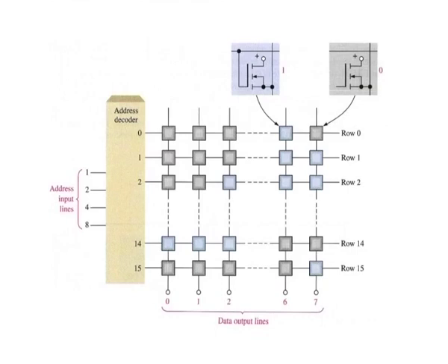This high is connected to the column lines through the transistor at each junction or cell where a 1 is stored. At each cell where a 0 is stored, the column line stays low because of the terminating resistor. The 8 data bits stored in the selected row appear on the output lines.